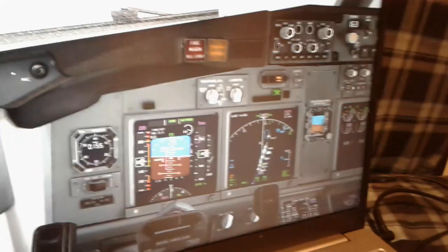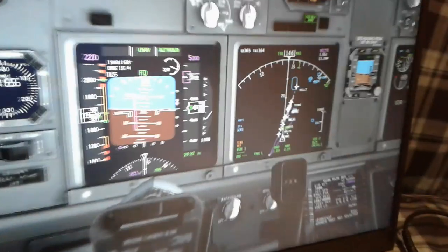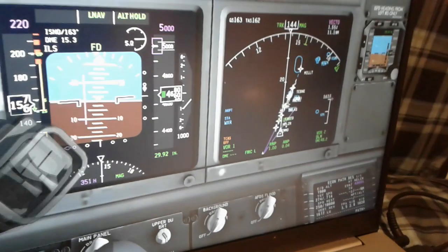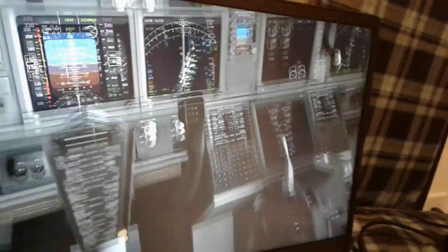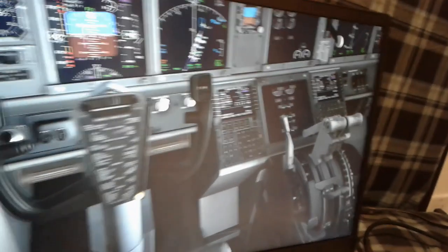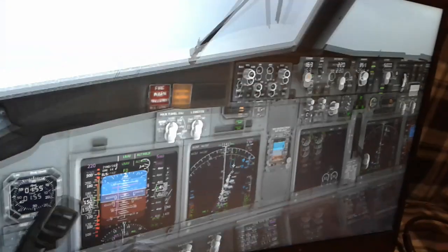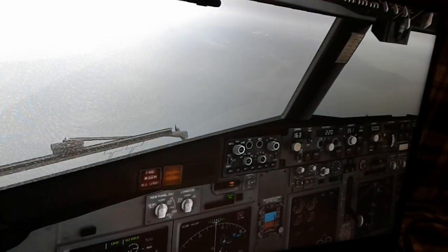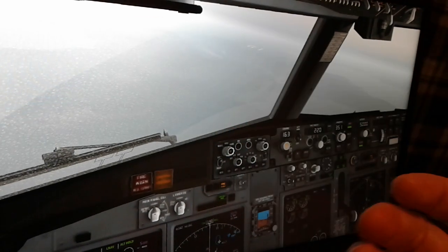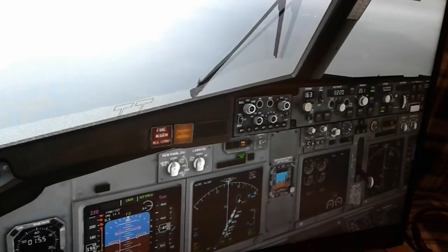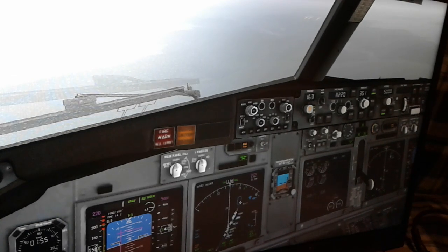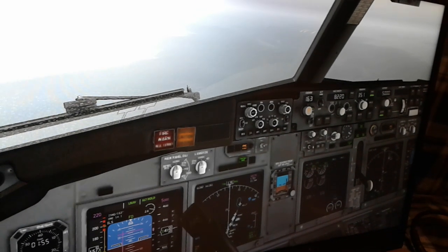We're gonna glide the airplane with idle thrust on the runway for landing. Have to follow also the ILS localizer, the glide slope, adding some thrust from time to time. You can see we have some wind. It will make the aircraft weathercock into the wind sometimes. So we need to use cross controls in case we have side wind.